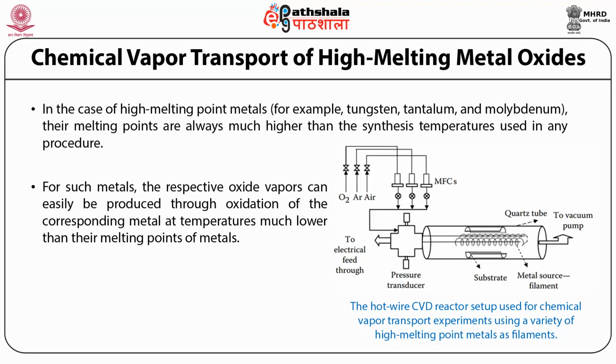The transport of the respective metal oxide vapors onto the substrate can be used to create metal oxide films similar to any CVD technique. However, it has been shown that under particular circumstances with low oxygen partial pressure, such chemical transport procedures result in the synthesis of respective oxide nanowires without the aid of any external catalyst.